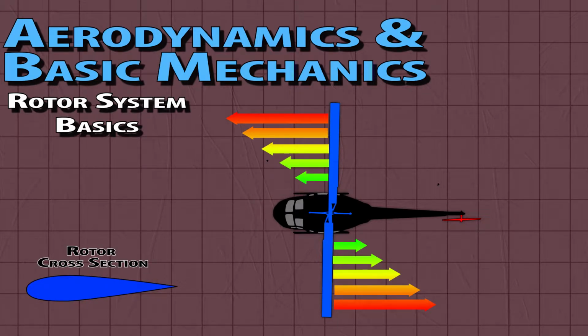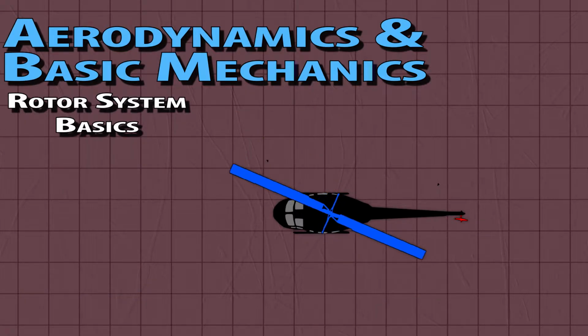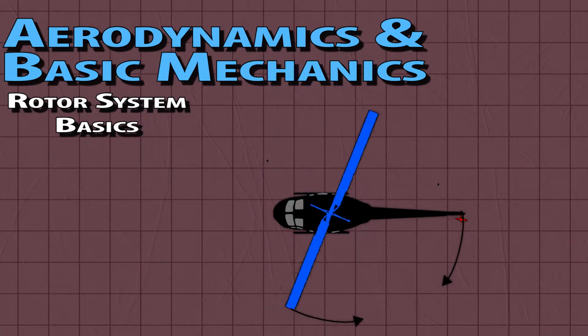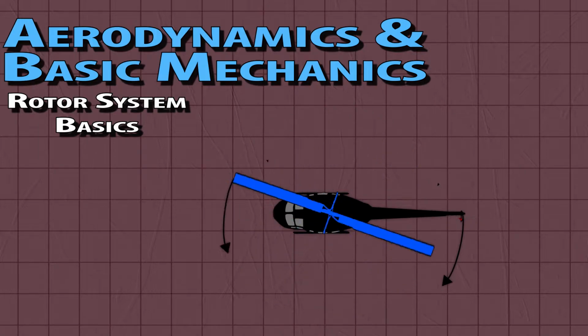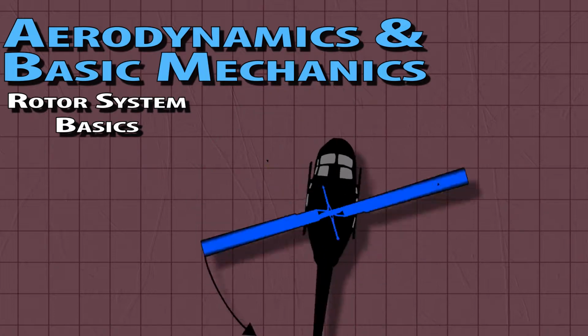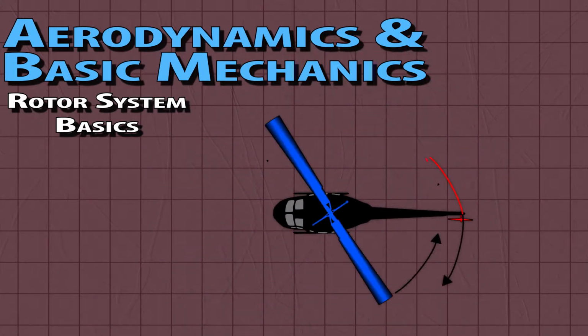The effort to spin the rotor creates torque. Much as using a power drill turns the drill bit a lot and tries to turn your arm a little, a helicopter's body will rotate in the opposite direction of the rotor if unopposed. Friction with the ground will do this, but as soon as you leave the ground, you'll start spinning. For this reason, we have an anti-torque tail rotor.